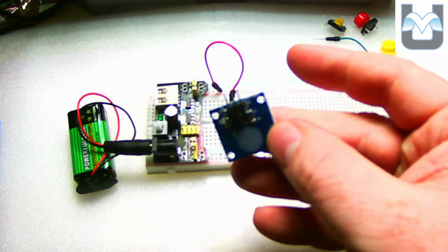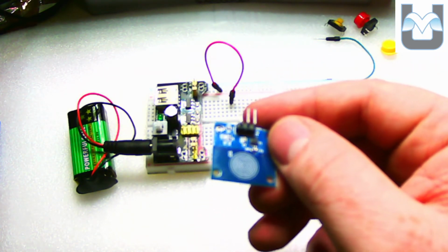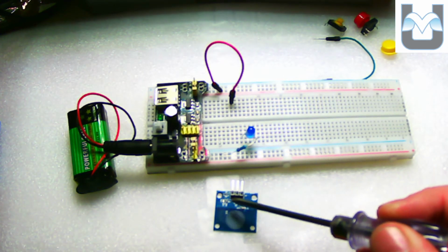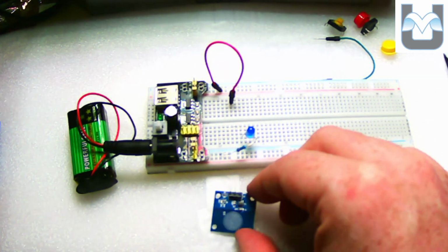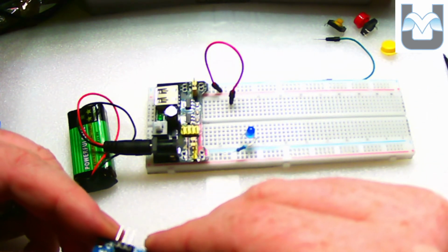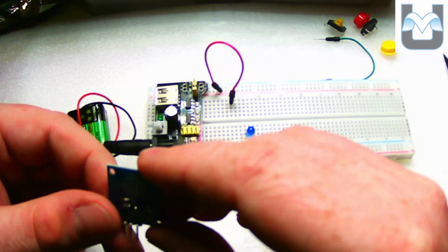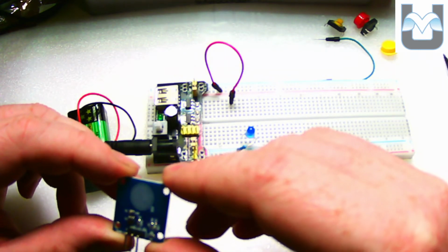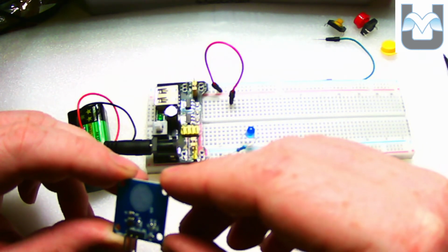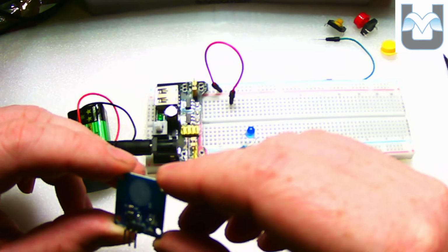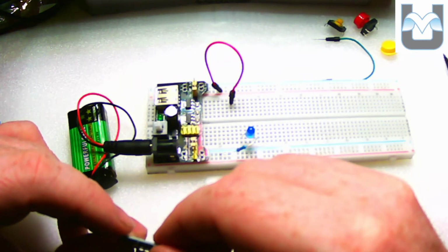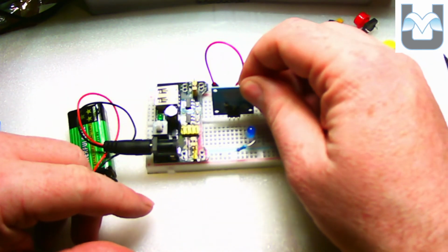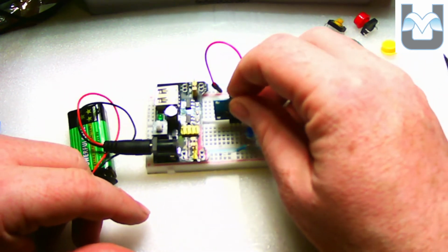and I can see, resolution's not going to be great on this one, but I can see right about here on your board, I can actually see three things written. The three things that are written here are VCC, which represents positive voltage, or your 5 volts in this case. I can also see ground, which is on the left, and that's obviously going to be our negative voltage, our black wires in the case of TinkerCAD. And I can see SIG, which is signal. So I'm going to go ahead and just straight up hook this up to signal, and I'm going to put signal where I have my LED.